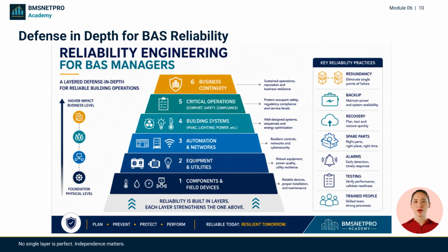Reliability is strengthened through independent layers: sound mechanical and electrical design, local control and safe failure modes, redundancy where justified, preventive and predictive maintenance, meaningful alarms and trends, verified backups, tested recovery procedures, critical spare parts, trained backup personnel, and incident learning.